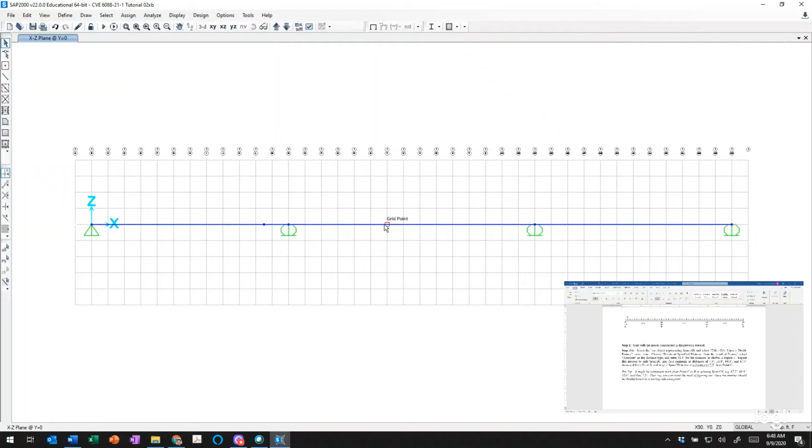All right, let me go ahead and do span BC, and I need 1, 2, 3, 4 nodes added. So this needs to go from one member into 5. In visual analysis, we were able to do that with one sequence of menu picks, but here we have to do 4 different versions. We have to split it 4 times. So in order to keep the X location of the splits manageable, I'm going to work from right to left instead of left to right.